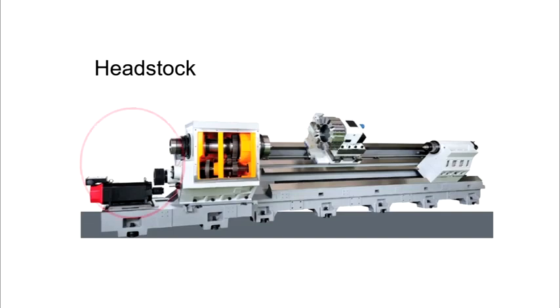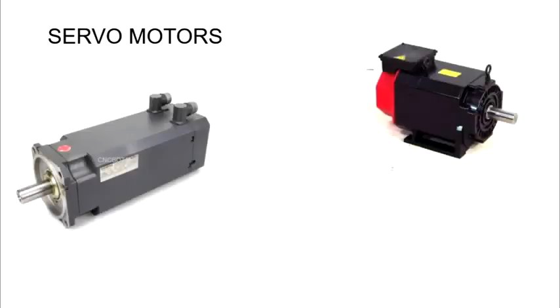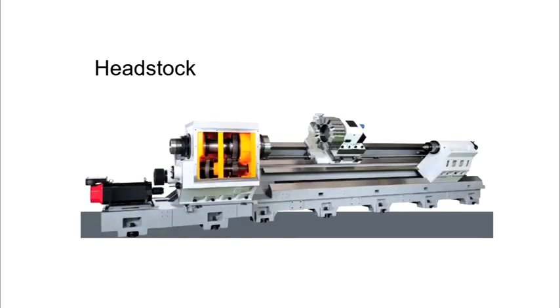At the left side of the spindle, the main spindle drive is connected. Normally in CNC machines, servo motors are used as spindle drives. And at the right side end, the work holding device is fixed. This whole assembly is known as the headstock.